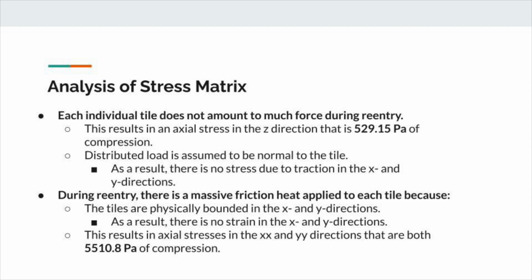The distributed load is also assumed to be perfectly normal to the tile, so there is no stress due to drag in the X or Y directions. The only stress in the X and Y directions is going to be due to thermal stress. In addition to the axial loading, we are talking about re-entry, so there's also a great deal of heating due to friction that has to be considered when calculating the stresses in the tile.